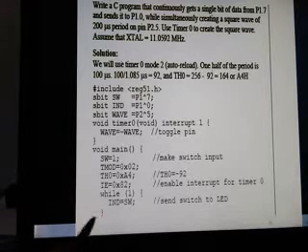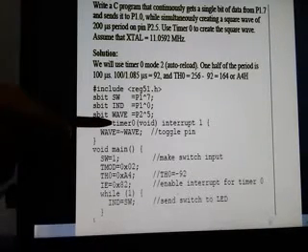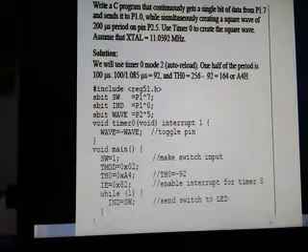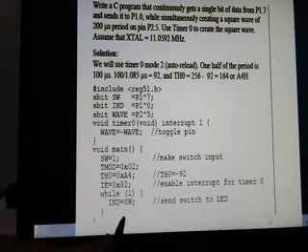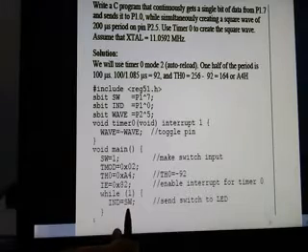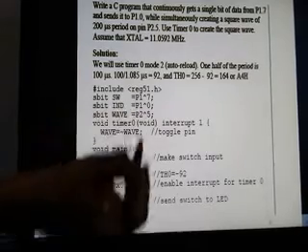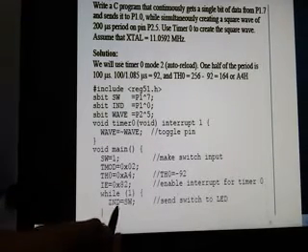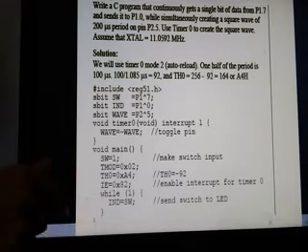So when the timer is started, the upcounting starts. Okay, whenever the timer overflows, then the control goes from the main function to the timer interrupt function. Till that time, will the microcontroller remain idle? No. The microcontroller will send the value of SW, that is P1.7, to P1.0, that is IND. So IND is equal to SW. This is what you are going to do in the main function. End the main loop, end the while loop.